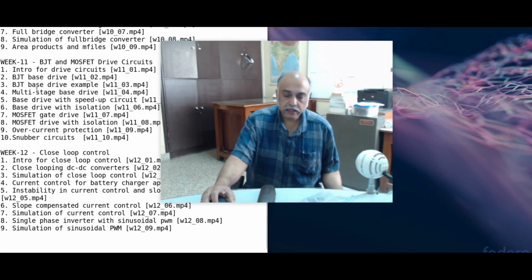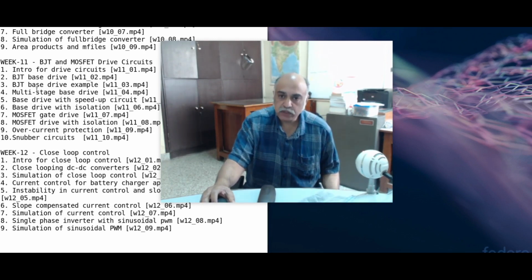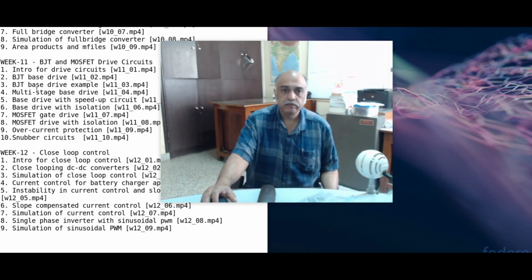In the recorded videos of 2018, we had used gEDA, gschem. It's also an open source GUI based schematic capture, and the schematic which was captured was converted to a netlist, and ngSpice was used to do the circuit simulation.